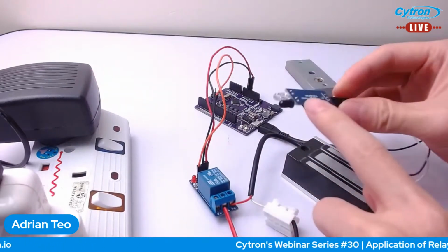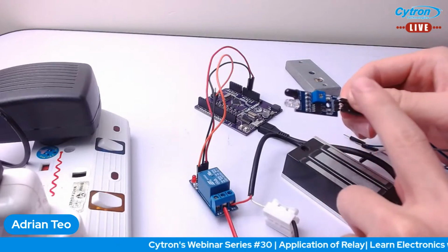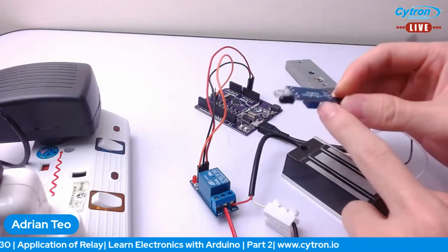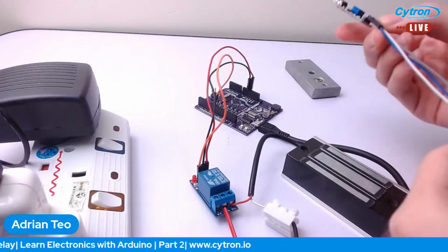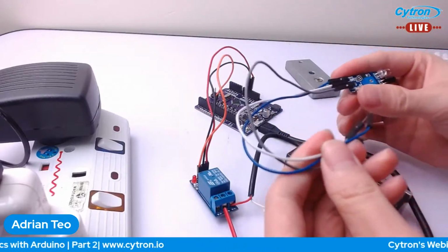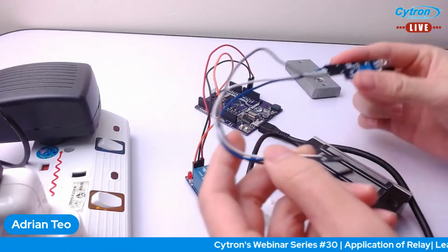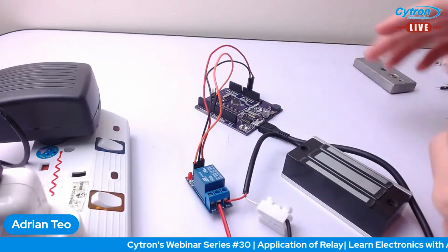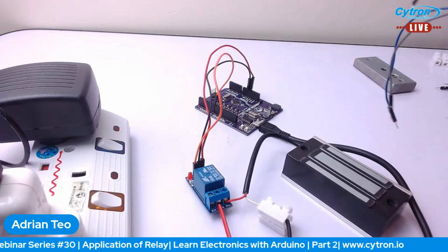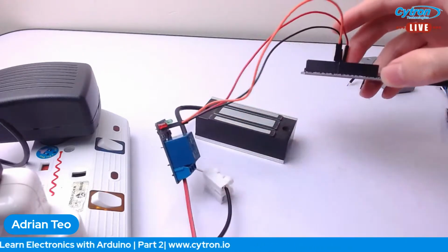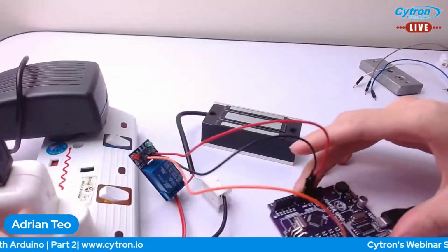Right now it's not an analog signal, it's a digital signal, so it can tell you whether there's an object in front or there's no object in front. That's it. It can't measure distance. For this case, it's not analog. And then connected to 3 male to female wires over here. And now I connect it to my Arduino. So for the ground, okay, let's move this to the side so that you have a better view.